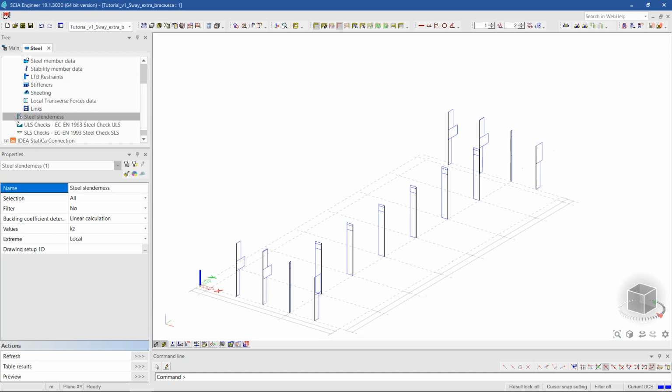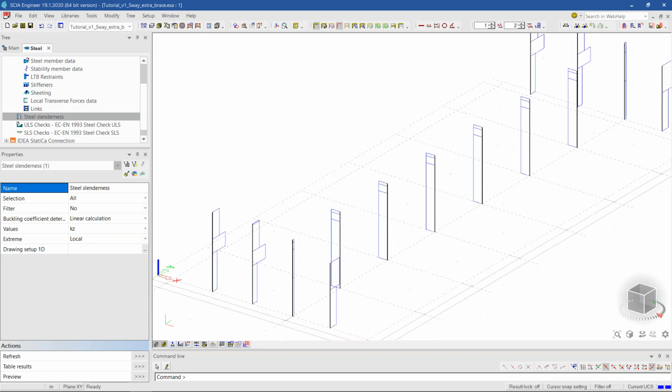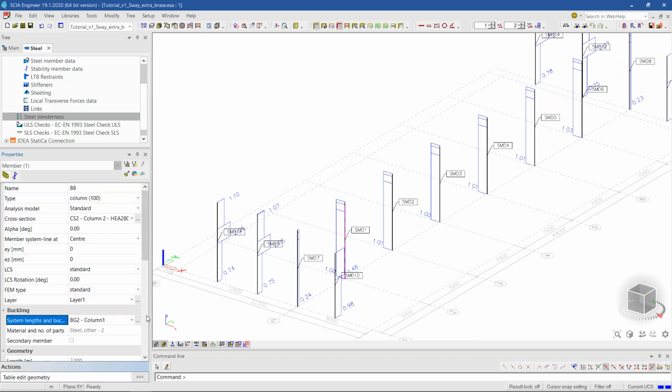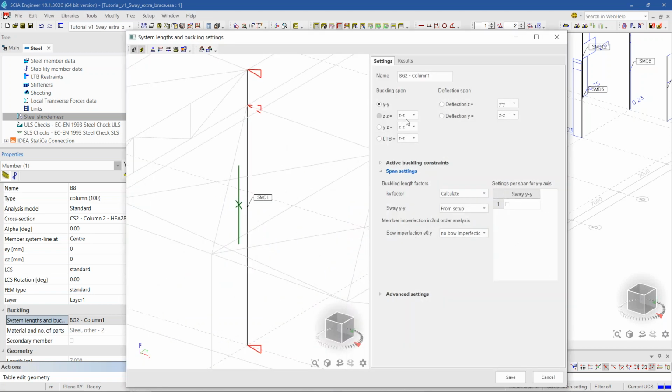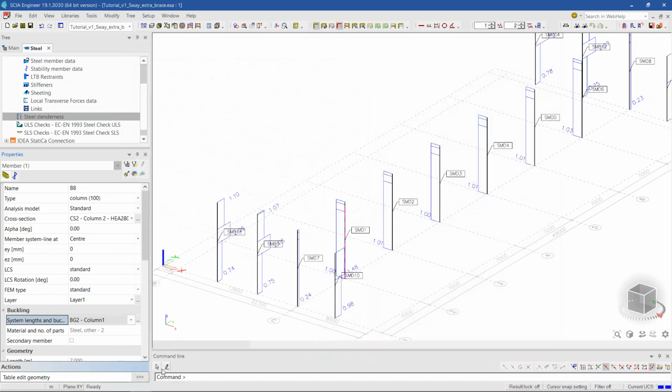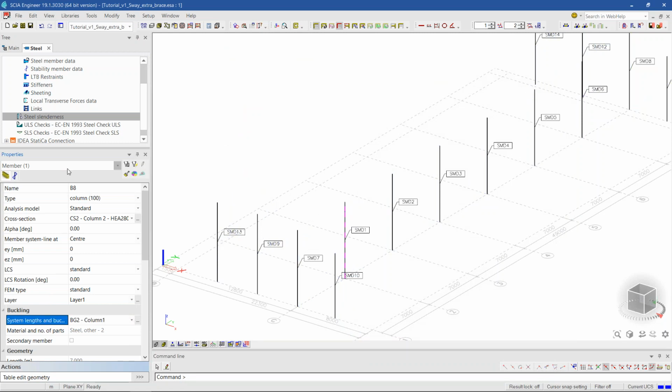Another thing that I find is a problem when you are using stability analysis is that here, if you go to the buckling settings, what I've done is I have disabled the buckling support in this direction. I saw during the stability analysis that this is displacing like one member. And if I would activate this support here and I obtain a shape which is not affine to my deformation,